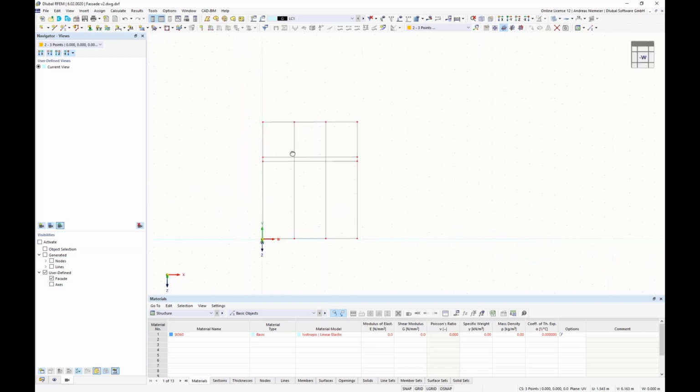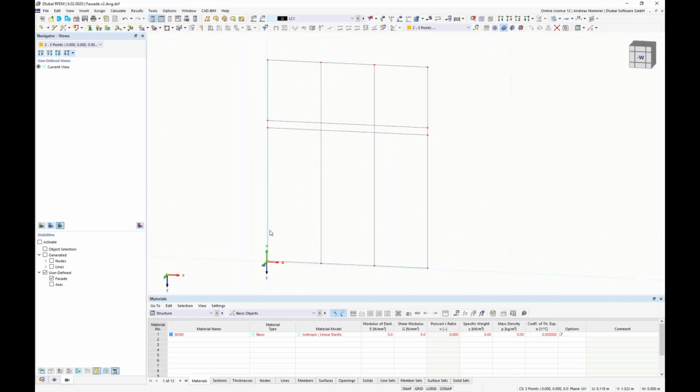So now we know exactly how big the facade is, what the dimensions are, and what the grid spacing is, and we can go ahead modeling this structure. For this, of course, we take a closer look at this model and see, okay, the drawing of this facade has lines from left to right that draw over these mid elements. This is not really suitable for RFEM because you would have to define some contact definitions. So we repair it with this intersection function and create single lines.